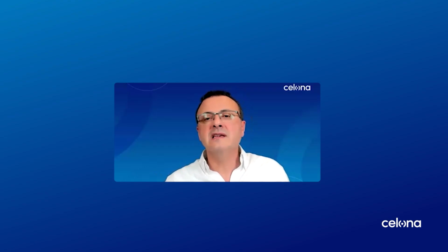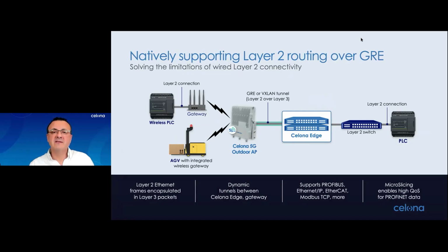Now, once you start connecting these devices through gateways, the next challenge becomes, specifically in industrial environments, what happens to the devices behind the gateways? Do we have full visibility, right? Many of these devices are not even IP native, right? And they may be relying on layer 2 industrial protocols such as Profinet, EtherCAT, EtherNet/IP, Modbus TCP, Profibus, all of those. In many cases, the PLCs and controllers on both ends expect to be on the same L2 domain, layer 2 domain. So that's where the traditional approach starts breaking down, and there is some ongoing work in 3GPP to support these use cases.